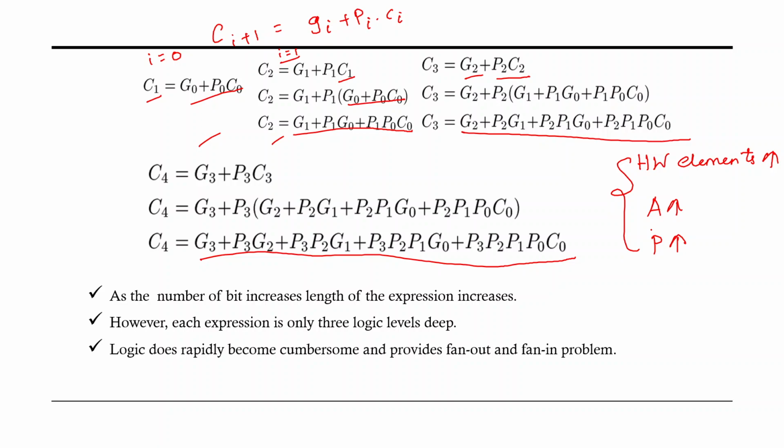But what's the advantage here? I can compute C1, C2, C3, C4 parallelly. So the time consumption is very much less. The speed is very much higher in this carry look-ahead adder. That's the advantage of a carry look-ahead adder.